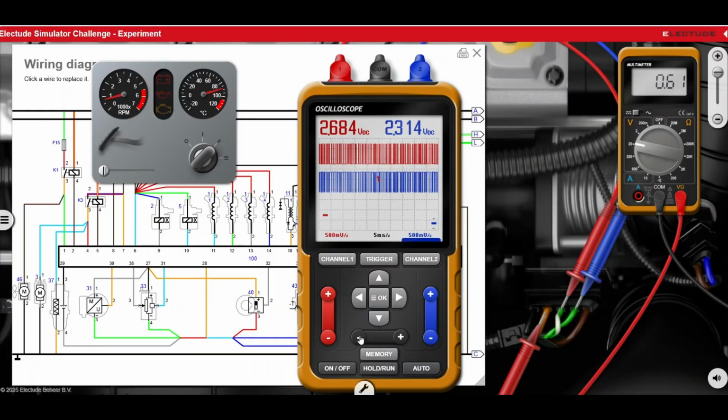Yeah, I can play with the time setting so that you get to see more detail, more or less detail. Now you are seeing more detail. But it's not always that more detail is good. Sometimes you want less detail, so you zoom out like I'm doing now, so you see here. Now I have overdone it. Now I can go the other way. Yeah, that's a good CAN signal.